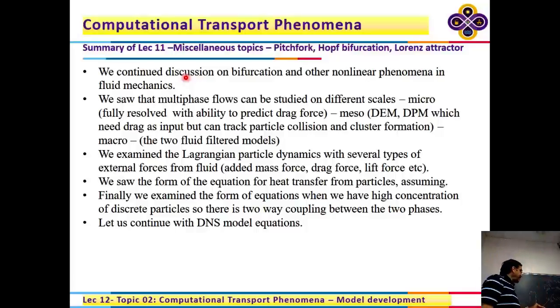In that case, you will find that the pressure has to be solved. So one trick you may want to do, if you really don't want to calculate the analytical result and put it in, is put this velocity as 0, put these as walls, solve it, and then you will find that you get the correct pressure profile. Start with that profile and then turn that into a symmetry condition.